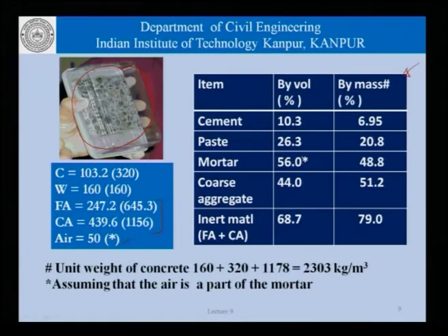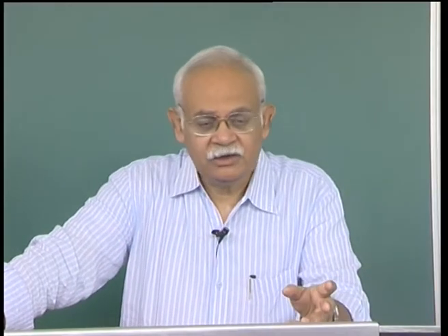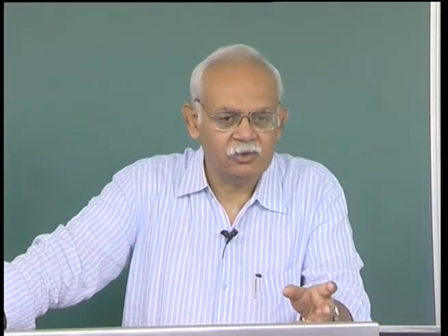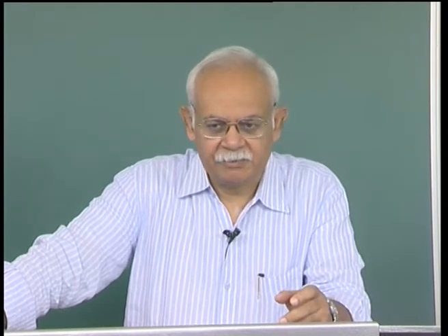Of course, what I have done with 56% is that I have assumed air to be a part of the mortar, and that we discussed in the last class, and the reasons were discussed there, that air can be considered a part of the mortar. The argument can be extended: why should air not be considered a part of the paste? Well, you are free to do that, so long as you know that that is what you are doing, that is the assumption that is being made.